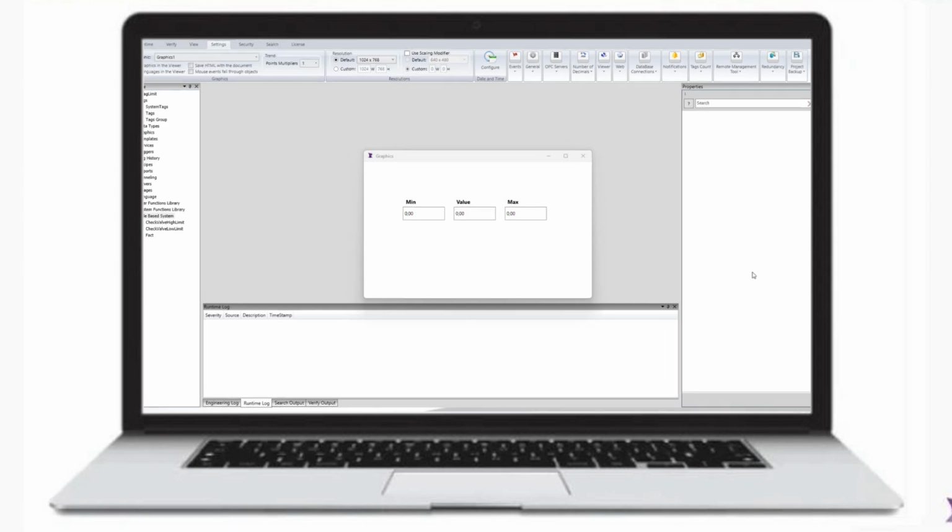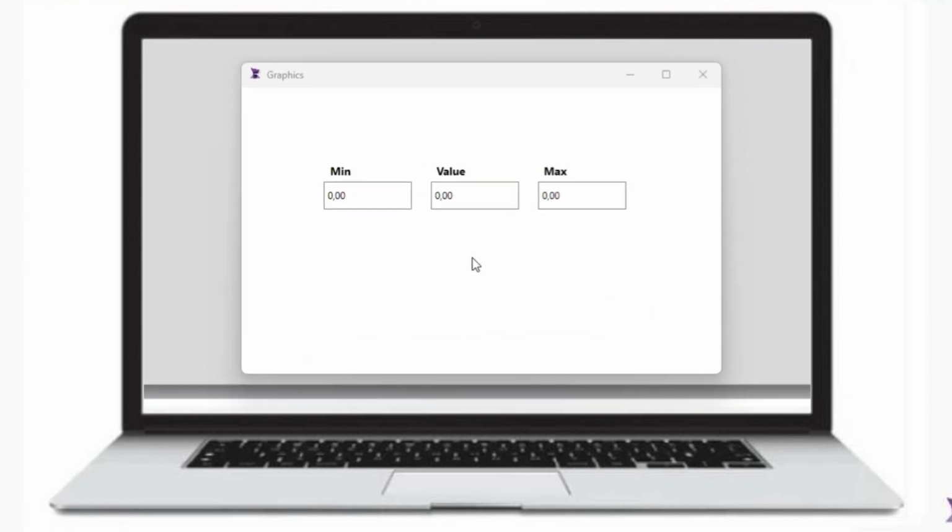When the application loads, we can see the valve is still at 0. Let's set a max value as 100 and a min value as 12. As soon as we change the min value, the rule that validates the min limit triggers and sets the valve value to 12, which is the min limit. We can change the value of the tag inside the range, but if we trespass the higher limit, the valve will also be corrected to match the max limit.